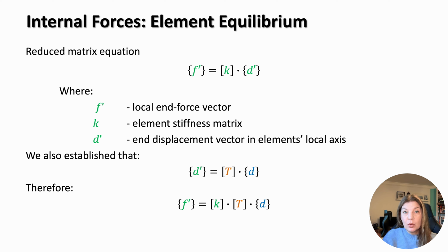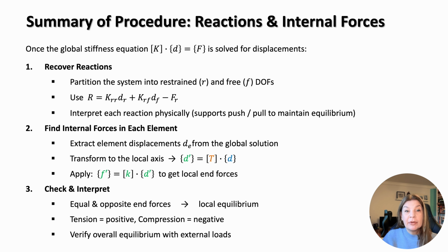That means that if we want the forces and moment at some place in the middle, we need to create a node there, or we need to figure it out from different types of solutions after we have the end moments and forces. Before we start solving a frame example, let's quickly summarize the full procedure.